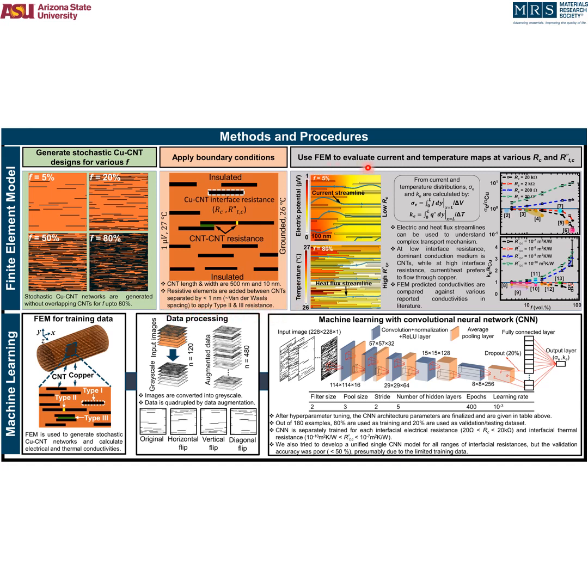FEM simulations solve the physical equations to get current and temperature distributions, which are then quantified into electrical and thermal conductivities. We also compared our work with previous work to estimate what are typical interface resistances in bulk scale composites. After generating examples with FEM for machine learning, we perform a simple data augmentation technique to quadruple our training data.